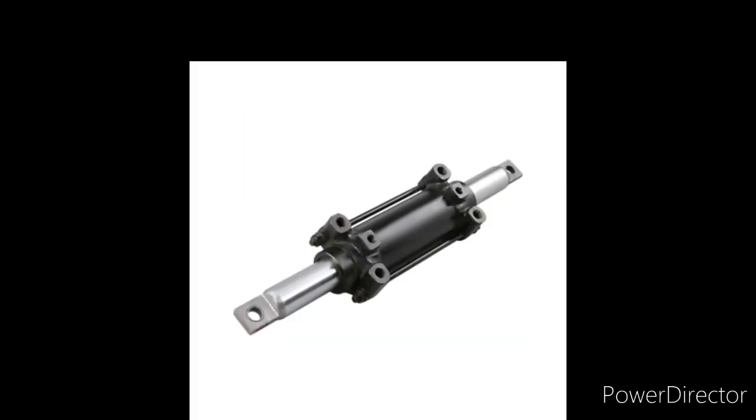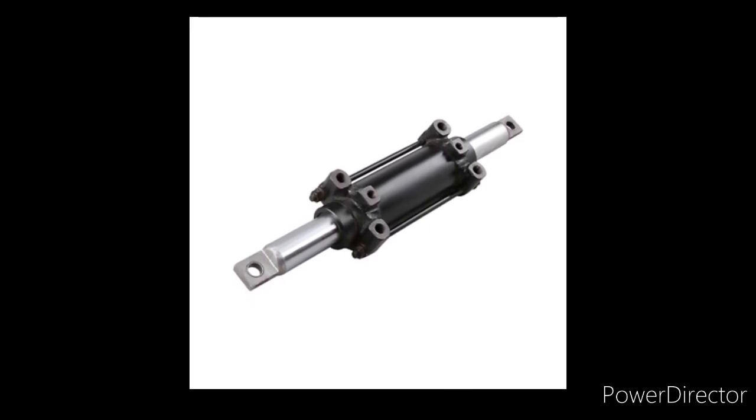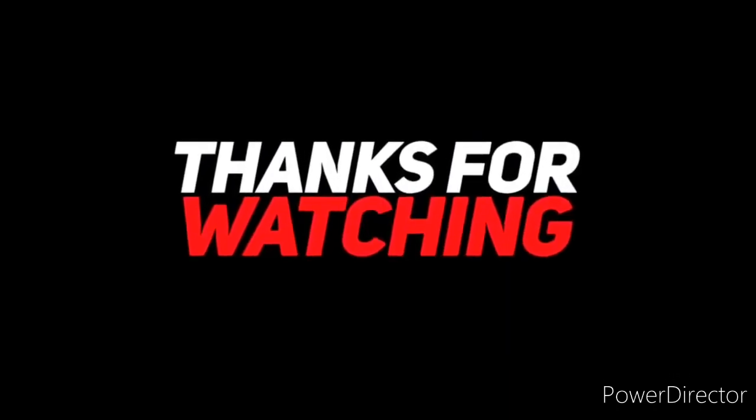The hydraulic pressure comes from a pump driven by the vehicle's engine or motor. A double-acting hydraulic cylinder applies a force to the steering wheel, which in turn steers the road wheels. The steering wheel operates valves to control flow to the cylinder.